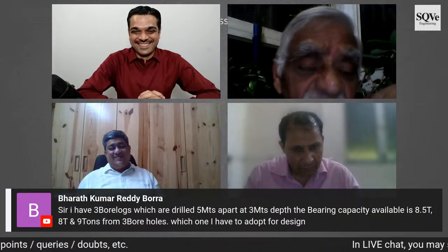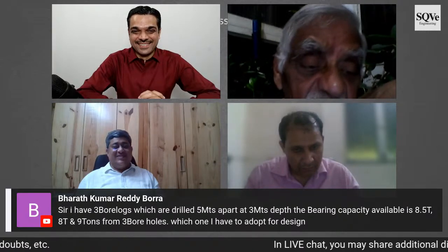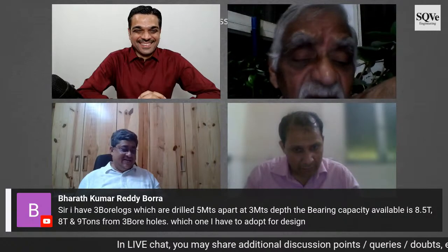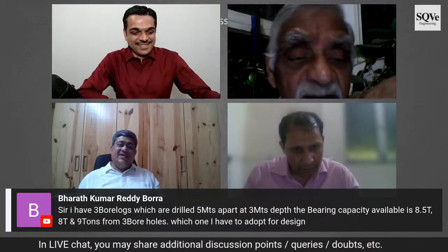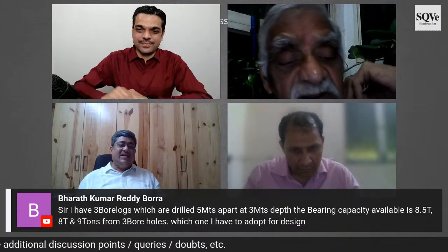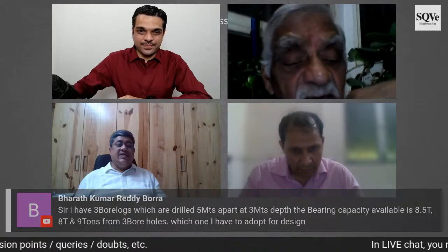So probably he has been generous in going 3 meters. He had a longer ladder. But I think the concept still remains of a 1 meter by 1 meter pit to understand the soil. And probably somebody would have collected a disturbed sample or otherwise to get a feel of what it could be. It's a very common practice.